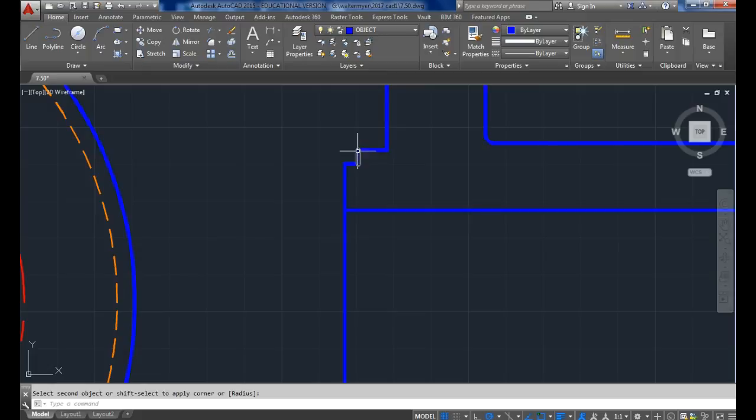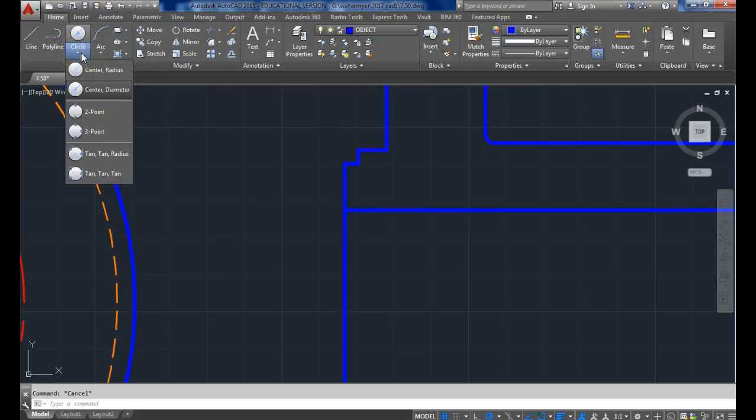This is one that is listed different. This one's a radius 0.19, and you're going to run into a problem if you try and do radius 0.19. Select one, select the other. Invalid. Fillet radius too large. That means the space is too small for the partial circle you're trying to put in there. So we have to cheat the system a little bit.